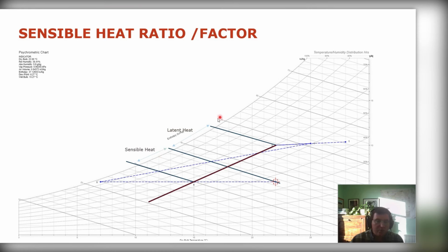And the difference between the two is the latent heat of the room. And what I can also do is go from this point to that 0.6, and again, check the enthalpy readings on both. And this is purely sensible heat in this case. So I'm just warming up from 6 to this point here. I'm just changing the dry bulb temperature. My absolute humidity stays the same, it's a horizontal line. And then I check my enthalpies. And the gain here is my gain of the sensible heat.